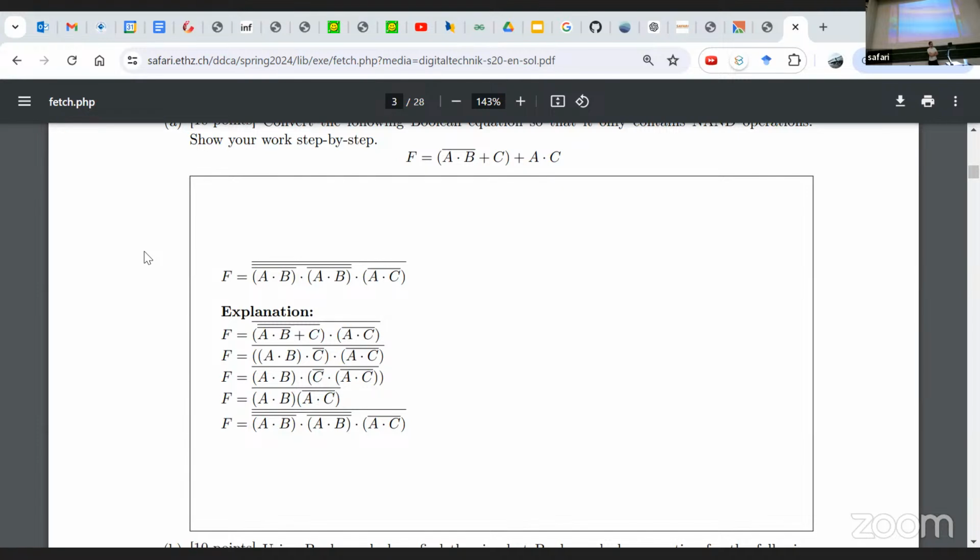Mostly correct, yes, but in hardware, you could have also inserted a no operation as well. But it's not possible in the instruction set to make a stall. The compiler cannot make a stall for you, but during compile time, you could realize from the scheduling of the instructions that you might have read after write hazards, meaning that, hey, I'm reading too soon before the write has completed, and for that, you might try to push them apart.